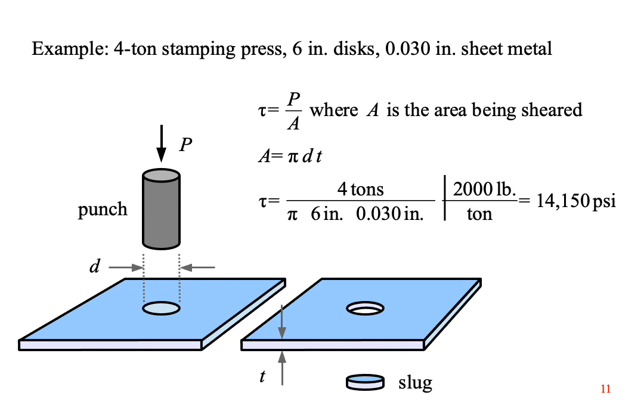If the shear strength of the sheet metal is larger than this number, then you can't make the part. If that's the case, then you have several options. You can use thinner sheet metal, weaker sheet metal, a higher capacity press, or a beveled punch that doesn't cut the metal all at the same time.